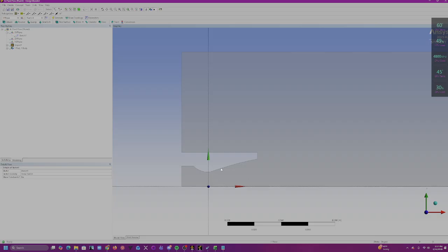The reason why we're doing this is, first, we can make the mesh a lot easier to work with. Second, we want to measure the actual exit conditions once we run the simulation and get the post-processing results, right? So that's the reason why we're doing these splits. So let's go ahead and get started on sketching.